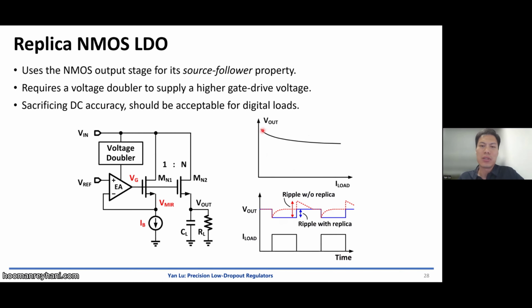For the DC load line, in some designs, we intentionally make the output voltage change with load current, right? That is good for load transient because we have more margin. We have doubled the voltage headroom for voltage undershoot and voltage overshoot. Another benefit, if it is a digital load, at heavy load, we have low supply voltage. We make sure the low supply voltage is high enough to maintain the high performance digital circuit operation.